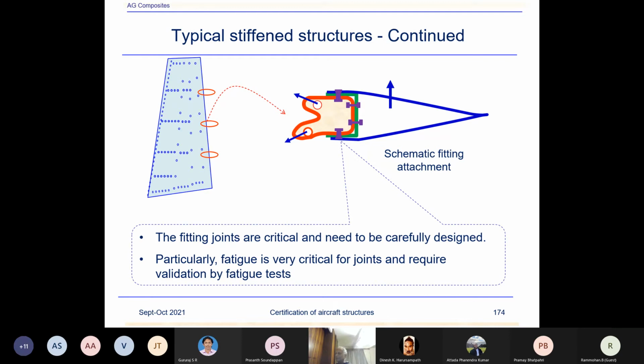Due to the fatigue cycling, the friction may be affected. So fasteners may start rotating if it's not a properly clamped joint. Or there are many members like shims, usually soft shims, that degrade the joint. So after some time, it may start rotating the fastener. Once the fasteners start rotating, that's the end of life.